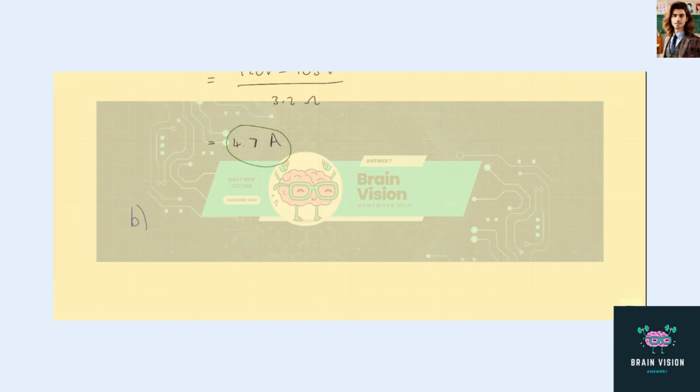Next, for part B, we want to know the power that is delivered to the motor. So we'll call the supplied power P subscript supplied, and this is equal to the current I times the potential difference VAB. So that's the power that's being supplied to the motor, and that's 4.7 amperes times the potential difference of 120 volts, which gives us the supplied power to be 564 watts.